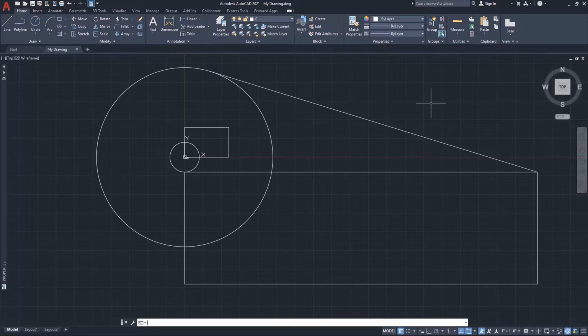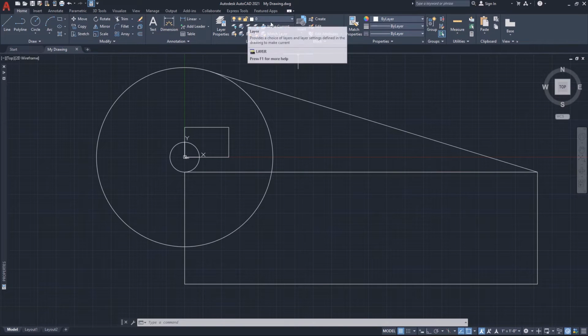In this way, layers serve two main purposes: to separate different drawing elements and to control where and when we wish to see these different elements, both in model space and within our drawing layout viewport windows. At the top right of the Layers panel, we see a bar that has a series of icons, and at the right end of this bar, a pull-down arrow.